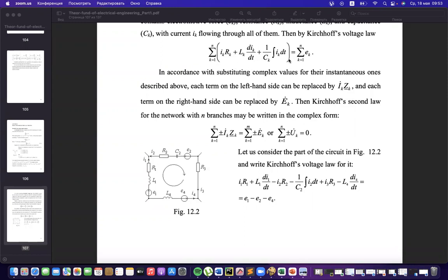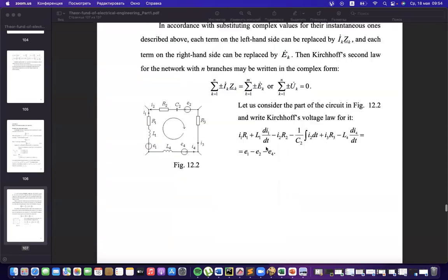It is when you are using sinusoidal functions. In this situation, you will obtain a differential equation or an integral equation for the sinusoidal function. It is quite complex mathematics. That is why we use complex vectors. You could represent these three types of voltages as complex vectors, using the so-called impedance, or total resistivity, of all three types of elements.